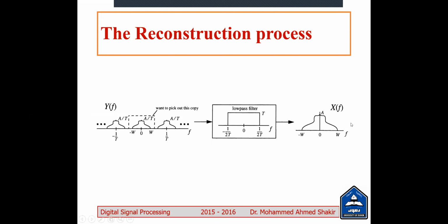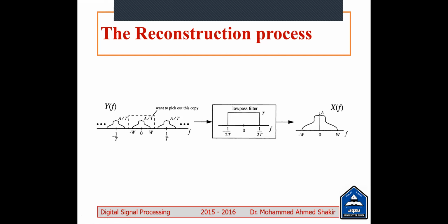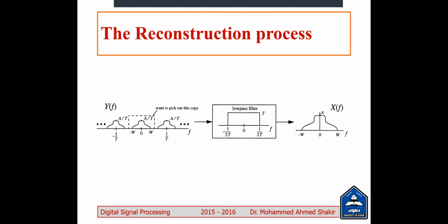Now, I'm going to represent this operation in the time domain. Of course, how? Again, we have the same thing. We said previously that multiplication in frequency, taking its inverse, will be convolution in time. Now, my question is, if you have a rect function in frequency, its inverse will be what? It will be a sinc function in time, due to the duality. I think you have studied the duality in the Fourier transformation, no? Okay.